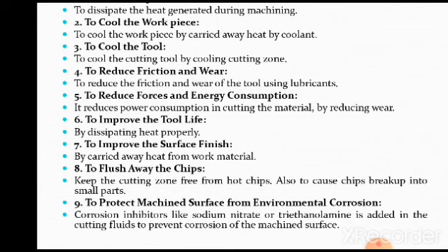To flush away the chips, this is also one of the important functions, keeping the cutting zone free from the hot chips, also to cause chips to break down into small parts. Because of the continuous flow of the cutting fluid, what happens? The metal chips will not have a tendency to stick either to the cutting tool or to the workpiece. They will start breaking up due to the continuous flow of the cutting fluid, so that it can flush away the chips.